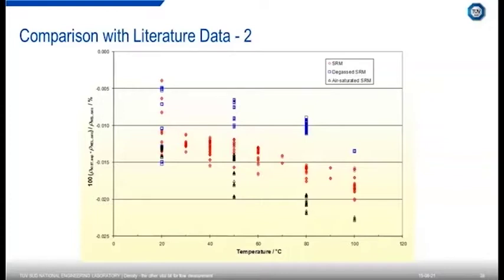And I found a paper which went into that in more detail, where they also had data for degassed and air-saturated samples. Now, the samples we were using, and also the PTB samples that I showed on the previous graph, were degassed. And you can see here, if I look at the comparison to the NIST degassed samples, the agreement is actually much better. It's only at the highest temperature, in fact, that we're much over the 0.01%. So, all in all, we've got good agreement with literature data, so we're confident that we can get low uncertainties in our reference fluid densities.